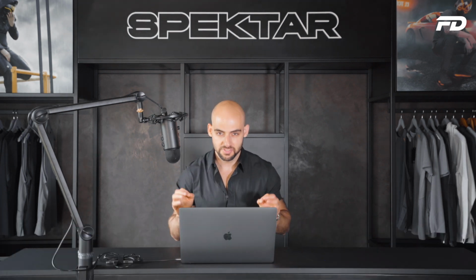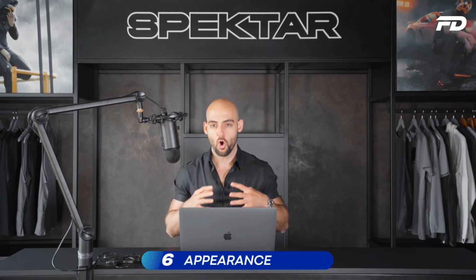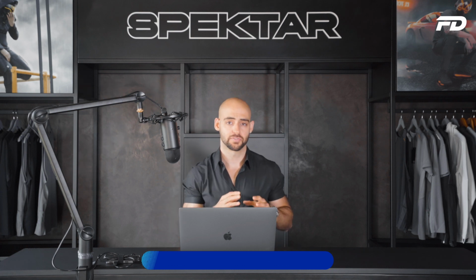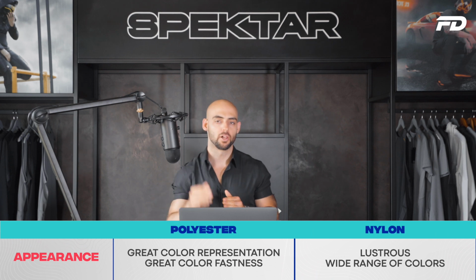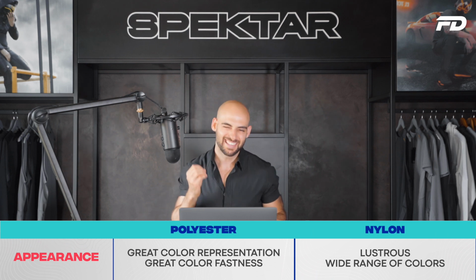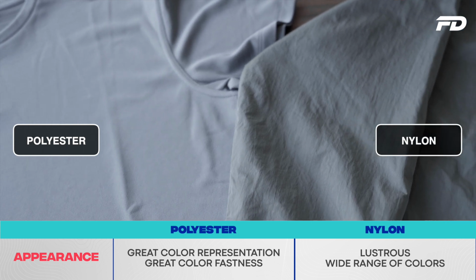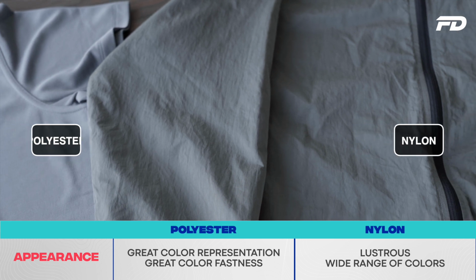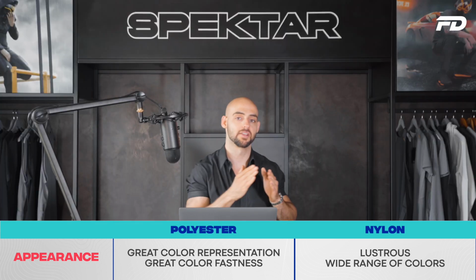When it comes to the appearance and the color fastness of both of these types of fibers, nylon on one side is going to be lustrous, and it is going to be available in a wide range of colors. It has a great color fastness, but when we compare it to polyester, polyester typically tends to come out a little bit more accurately in its colors, and it holds on to colors much better over time. You can also apply much more vibrant colors to a fiber that's made out of polyester versus something like nylon.